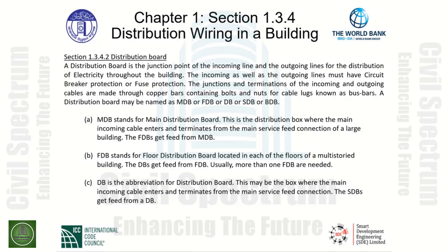As you recall from our definitions, MDB stands for Main Distribution Board. And recalling the definition, this is the distribution box where the main incoming cable enters and terminates from the main service feed connection of a large building. The FDBs get fed from the MDB.